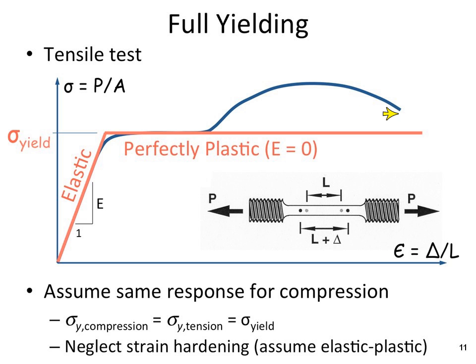and eventually the tensile coupon would rupture. Now, one thing I want to just mention is that this slide is in no way to scale. If this was 1 unit here, this would be approximately 10 units, and this would be approximately out here 100 units. So you've got quite a bit of ductility in steel, and so we try to take advantage of that in the design of steel structures such as flexural members.